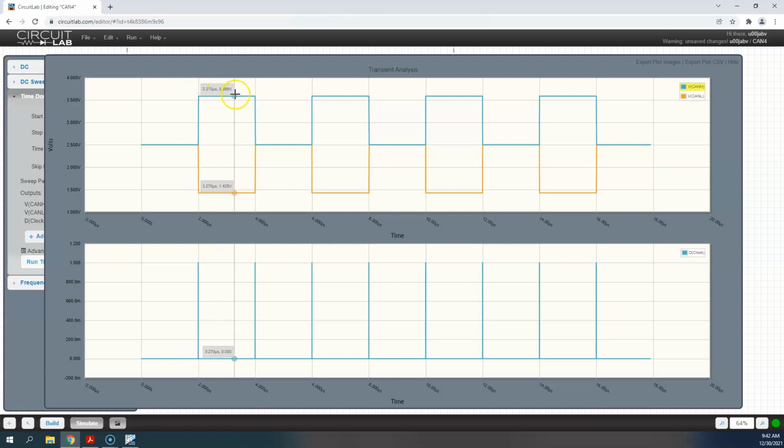As long as nobody else has done that, then this controller has the authority, or has the right, to go out and put its message on the CAN bus. Once it's finished, the CAN bus will be idle for a few microseconds, and then any other controller can use this.